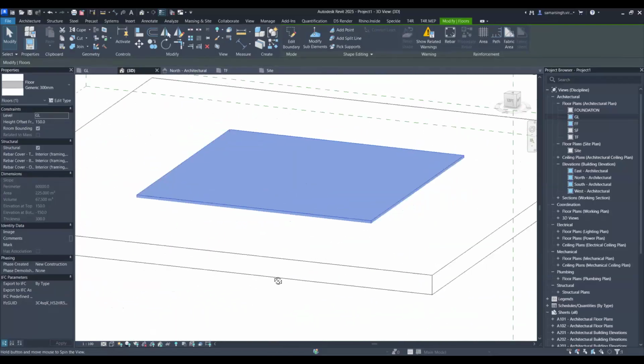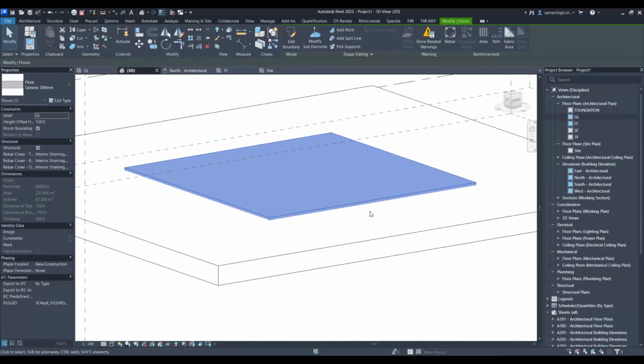Okay, one more pro tip and feature of Revit that people learn later on is that we can actually do a little bit of formulas within these data input boxes itself. So just like we have in, let's say, Excel, what I can do is to make it 300, I can enter the formula as equal to 150 multiplied by 2.